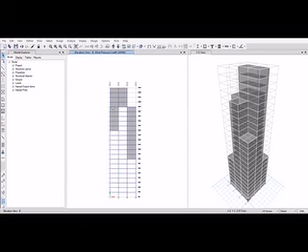The remaining cladding in the windward sides of the building which will be subjected to the wind load are visible. Select shells one by one. Using the all story option, select all the shells. Apply the same wind pressure coefficient of 0.08 in the windward direction to the shell and click on OK.